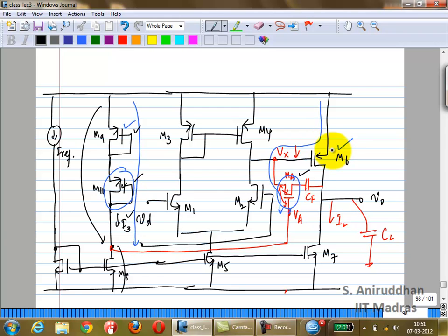So his question is, what happens when your input step is very large for the slew rate? So obviously, let's say this current is flowing like this. It not only has to charge CL, you have to charge CF also. Correct? Because you are trying to generate a very large voltage now, because V out is slewing. So obviously, correspondingly, there will be a slewing current flowing through charging the capacitance. We'll discuss that once we finish up with the basic compensation and so on. Okay, what will happen? How will your slew rate of your two-stage op-amp change?